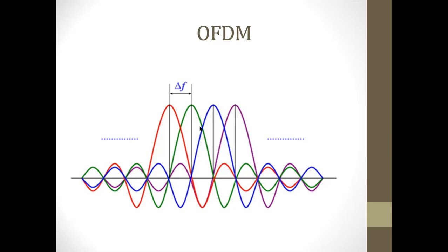Once you have the frequency range of one subcarrier, right there you can use the start frequency for the next guy. Well, practically you need a very slight margin, but ideally you don't need any margin, and this is the reason OFDM has become so popular.